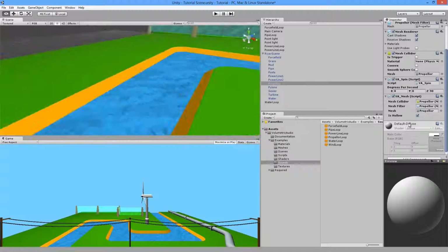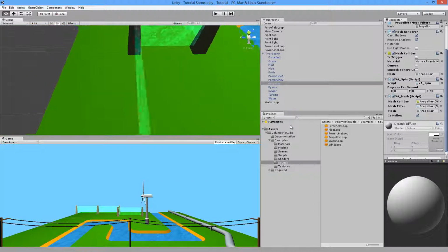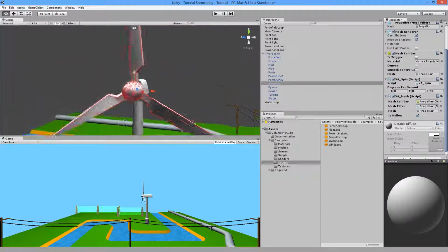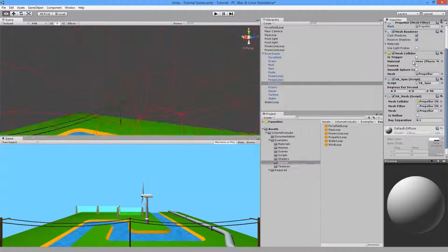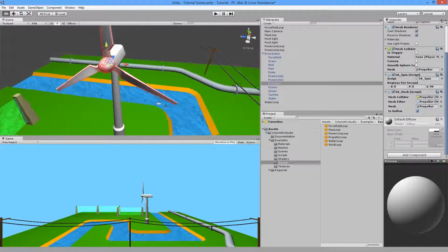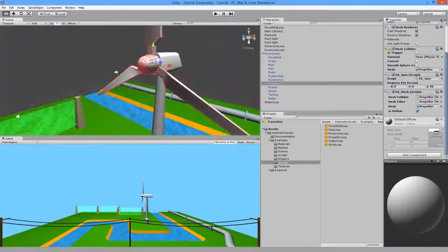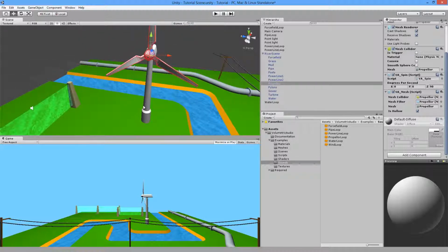of the mesh. So for example, the river is paper thin, as you can see, and the same with the force field here, it's paper thin, so there's clearly no volume to the actual mesh, so leaving that checked with is hollow makes sense. But for the propeller blades, maybe if you want the camera to enter inside, then you would uncheck this value, and the sound would be completely immersive when you enter inside the propeller blades. But in this case it doesn't really matter which one we choose. Just one word of caution: if you uncheck this and you have a volumetric mesh, the mesh itself cannot have any holes. For example, if you had a cube, a standard Unity cube has 6 sides, that would be a solid mesh with no holes.